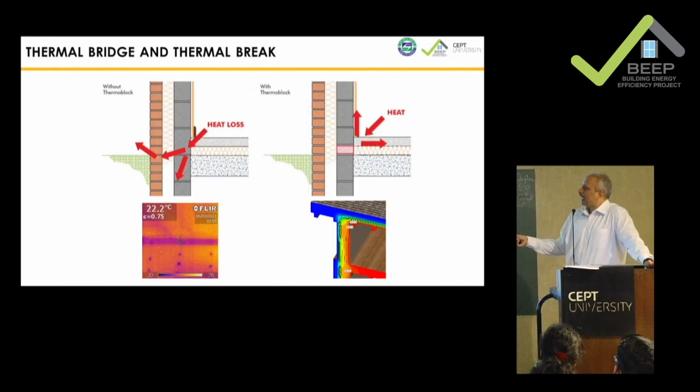So this is what happens when you have thermal bridging, but then you also need to take care that you avoid the bridging, right? So this is where construction technique comes in, the detailing comes into the picture.